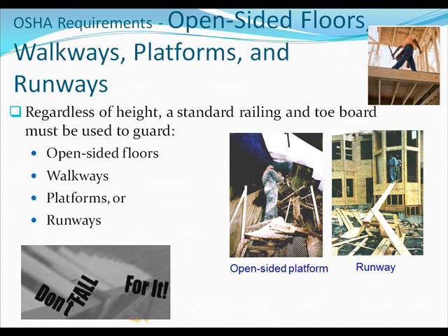Open-sided floors, walkways, platforms, and runways. Regardless of height, a standard railing and toe board must be used to guard open-sided floors, walkways, platforms, or runways.